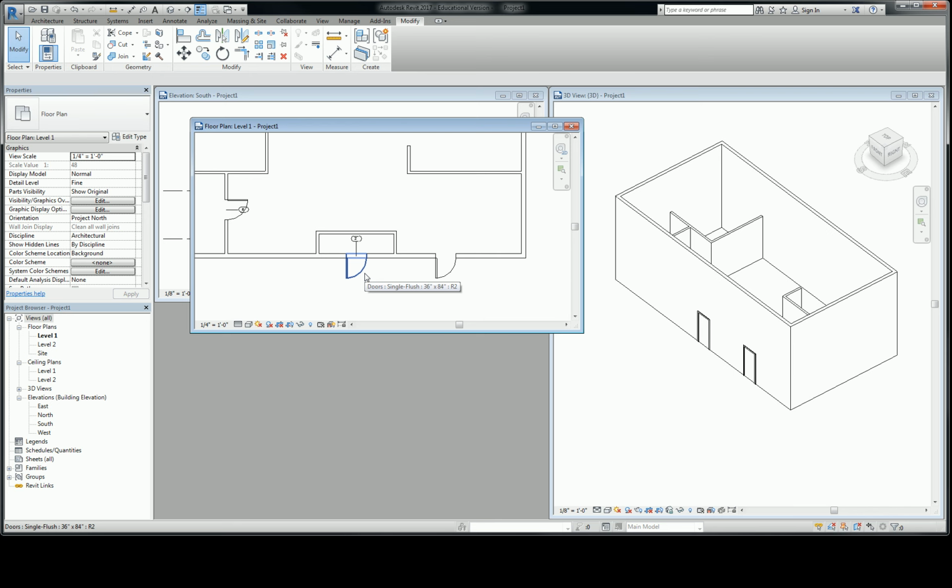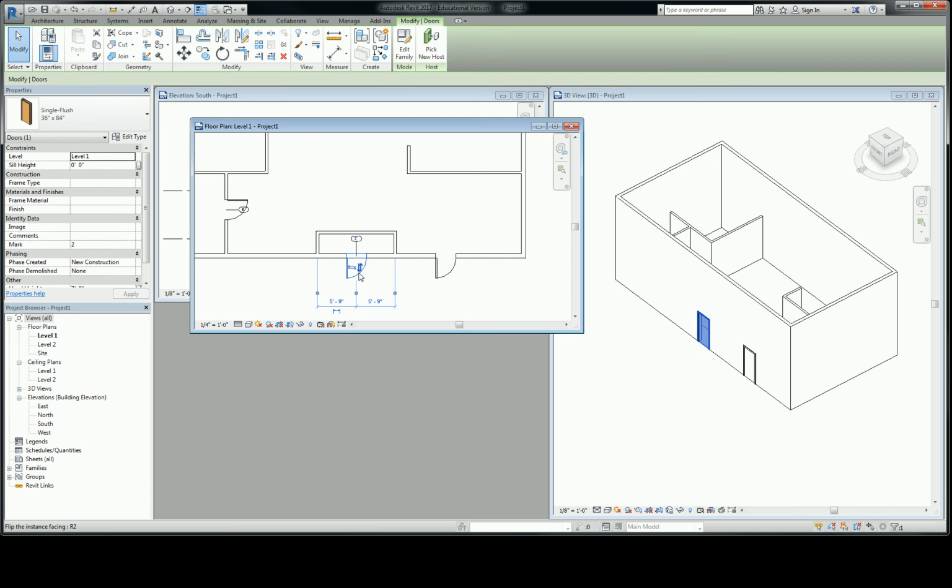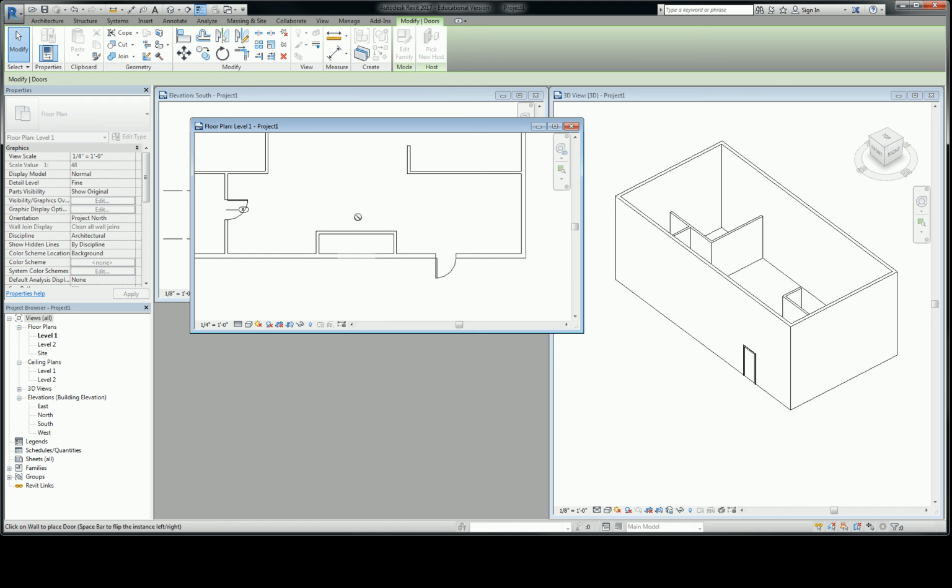Anyway, so the other thing that I want to show you how to modify is swapping out the wall type. So like I've already modeled these things as 8 and 5 inch walls. So I need to do 3 things in succession here. I need to move the door to the interior wall. I need to trim out the face of the wall that used to be the exterior wall, and then I need to change those 3 interior walls to be exterior walls. Okay, so that's done simply by selecting that door. I'm going to pick a new host, and I'm going to move it here.